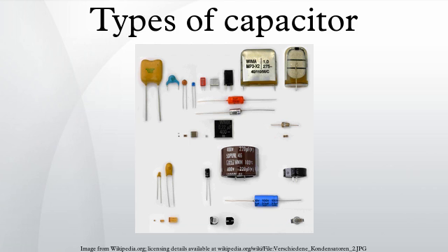Common EIA/IEC code abbreviations are C0G/NP0, P2G/N150, R2G/N220, U2J/N750, etc. Class 2 ceramic capacitors with high volumetric efficiency for buffer, bypass and coupling applications. Common EIA/IEC code abbreviations are X7R/2XI, Z5U/E26, Y5V/2F4, X7S/2C1, etc. The great plasticity of ceramic raw material works well for many special applications and enables an enormous diversity of styles, shapes and great dimensional spread of ceramic capacitors.